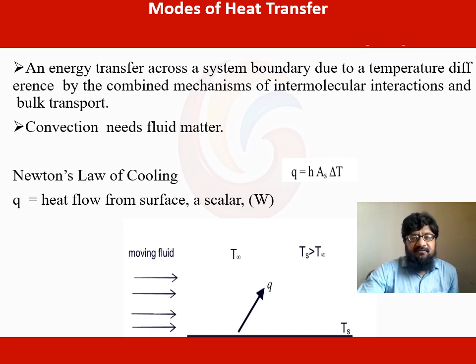The quantification of convection can be done by Newton's law of cooling, where the heat transfer is proportional to the exposed area, in which the h is called the heat transfer coefficient and As is the exposed surface area and delta T is the temperature difference.